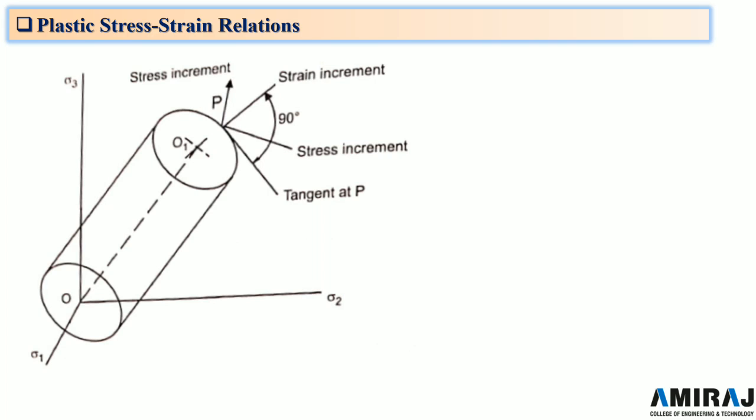Now in case of bulk plastic deformation, the elastic deformation may be neglected. If the material also does not work harden, it can be called a rigid perfectly plastic material. Similarly, there could be a rigid work hardening material.